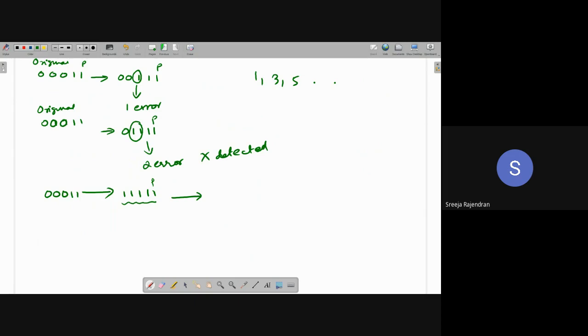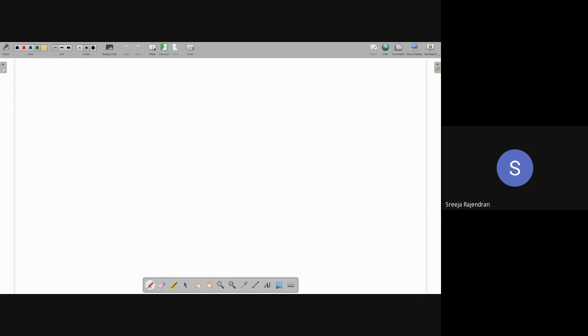Now let's start with combinational circuits, which I started sometime and then left. So now see, when I want to design any kind of a digital circuit, I call that process logic design. Designing of any digital circuit is called logic design. So if I want to analyze a circuit, I have to derive a switching expression that represents the behavior of that circuit, right? Every circuit that we had, we always got a switching expression from which we drew the schematic. Okay, so we should have a switching expression to analyze the behavior of a circuit.